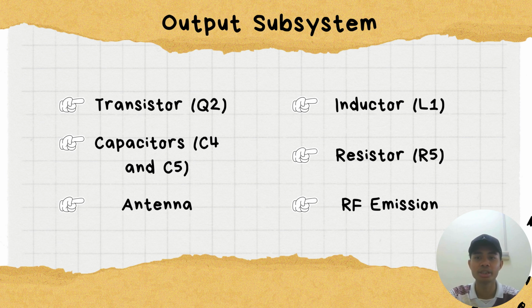The first one is transistor Q2. The last stage of amplification is this transistor. It amplifies the oscillator's modulated signal to a level where the antenna can transmit it effectively. For the transistor to function well and sustain the power level necessary for transmission without distortion, the biasing must be set appropriately.